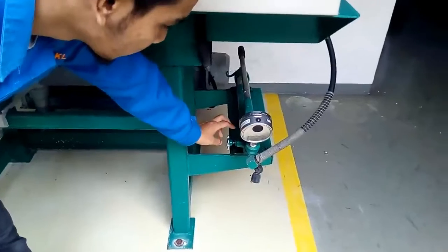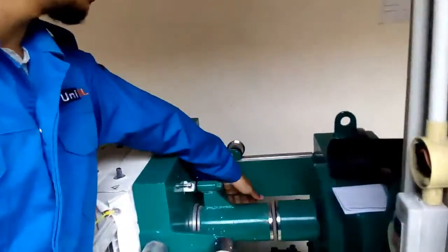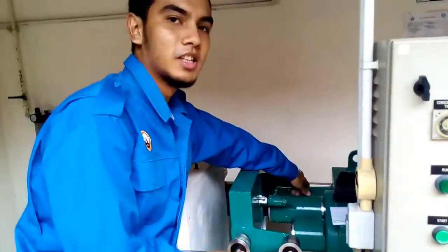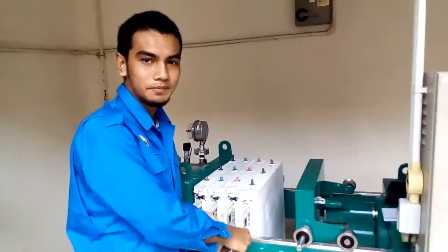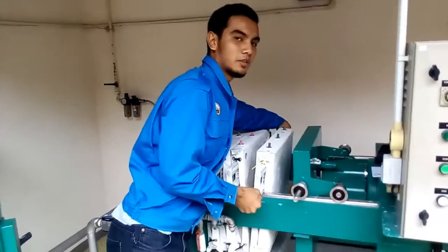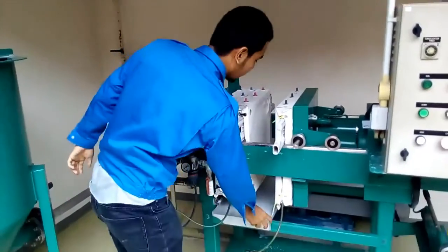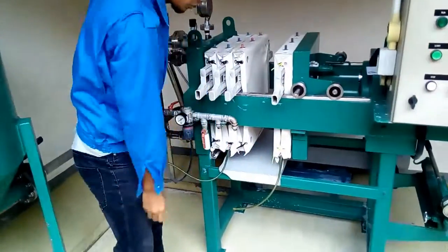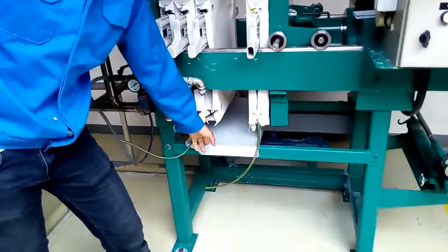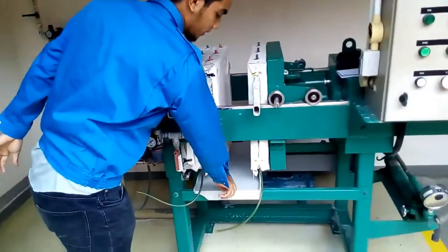After we turn this knob anti-clockwise to reduce the pressure of the piston, we move this thrust bar upward like this and move the moving platen backward. Okay, in order to remove the filter membrane, we move the filter membrane closer to the moving plate, and at the same time make sure that the tray below is present right here, so that any slurry will go right here.